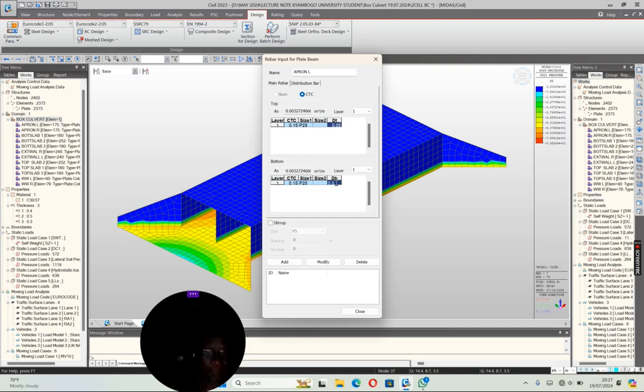The rest, you do what they call optimization. Then the distribution bars, I'm going to do 0.15 per 16 millimeter diameter. So here is the 16, and then 0.15, and then 16. Then the stirrup here, we are doing stirrups, shear bars. I'm going to do 12. The spacing can be 0.4. When you read the code, you will know what we can do. You keep adjusting. So it is one close member. I add.